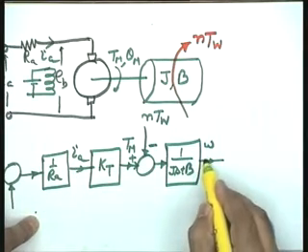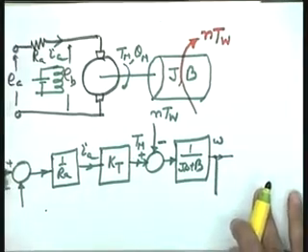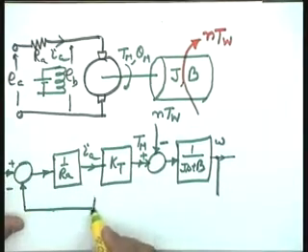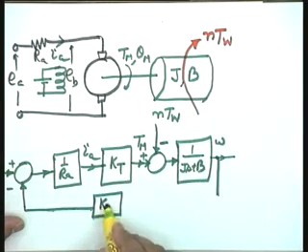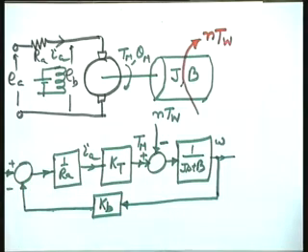Now, this omega you have to lift from here, because there is a feedback, and the feedback phenomenon is through the back EMF, and therefore, let me put a constant Kb here. So, this is going through the constant Kb into this error detector.